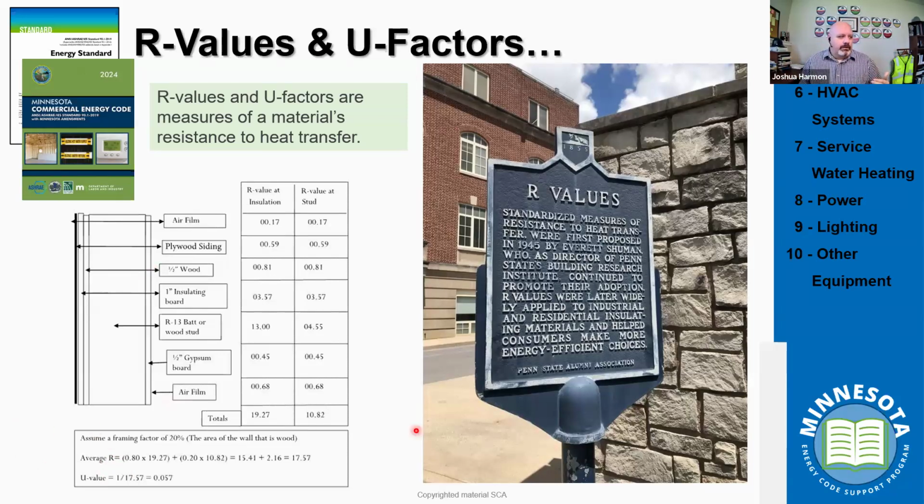The building trade-off method that we saw in the compliance path does that math on the grander scale of the wall, right? So if we're doing that, and again, maybe we should have thrown in some more pictures of the COMcheck or REScheck. But what you're doing is you're going to put in a value for a wall's square footage of wall area. You're going to tell it the framing factor, right? Are we doing 16 on center? Are we doing 24 on center? What are the different values of the cavity versus continuous insulation? It does all the math and spits out a very quick answer. Deducting, you're going to insert values for windows and fenestrations like we talked about in that wall envelope. But all those calculations go into it, and that's how we get the U factor.